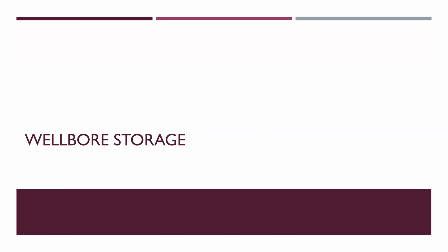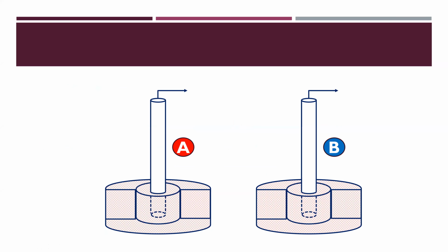Now, the first thing that the pressure gauge will feel is what is going on in the wellbore storage. This will be the first thing. So wellbore storage will have a great impact on the pressure coming from downhole, especially at early time, and after some time it will vanish. So at the beginning, we need to identify the wellbore storage and see what its impact is.